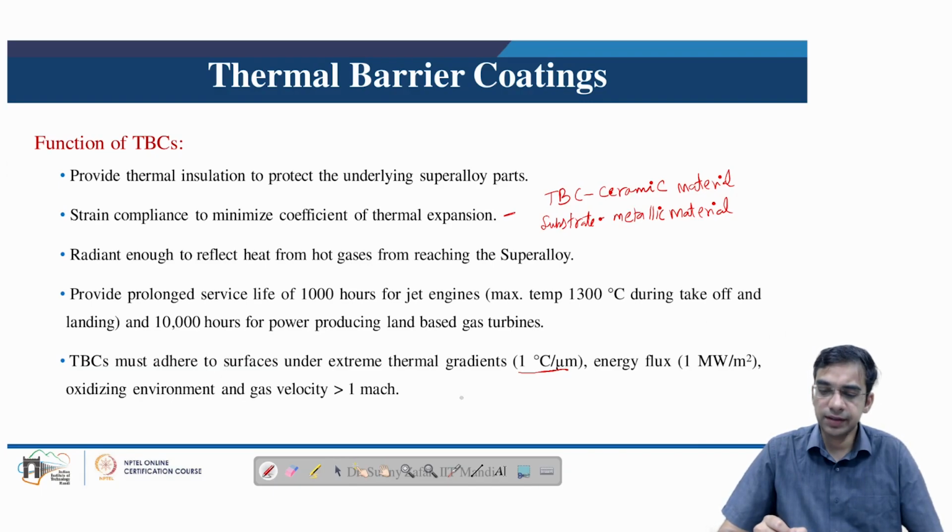Under such extreme conditions, the thermal barrier coating has to function, and functionality is not only sticking to the substrate but also providing strain compliance and proper thermal insulation to the underlying superalloy parts.